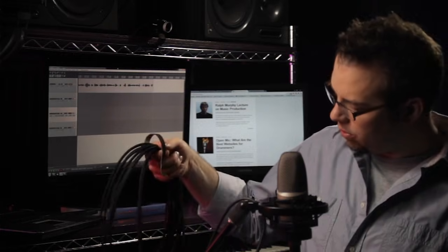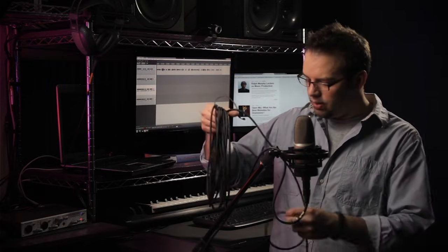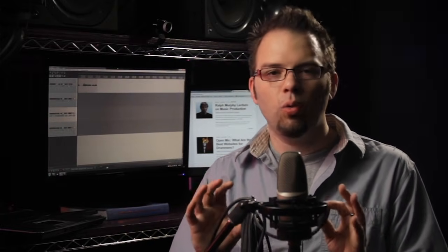Now, it's also okay to cheat the last part of the cable. So in this particular case, the last loop feels like it should be an under loop or a reverse twist, but it's perfectly acceptable to do the last loop and double it. So you do two twists in the same direction. You're drastically reducing the possibility that you will screw this up when you uncoil this wire.